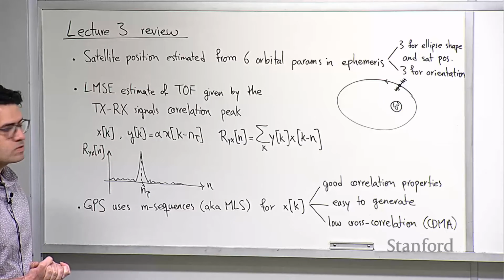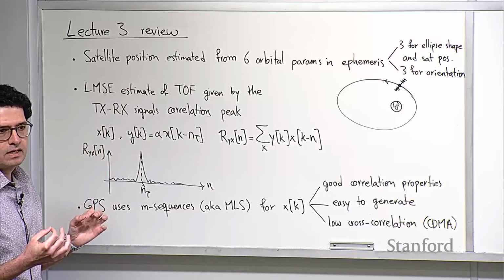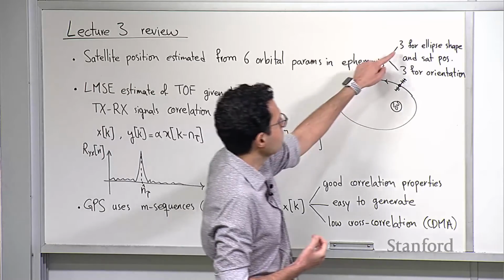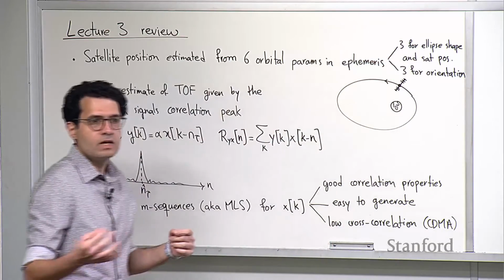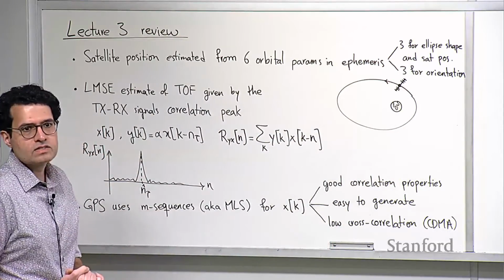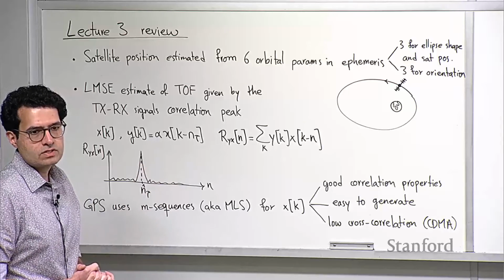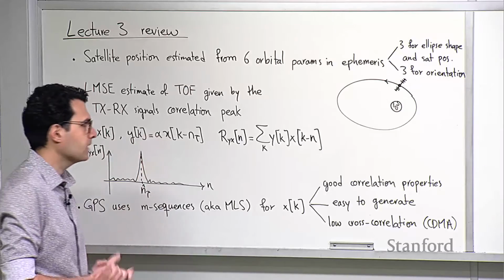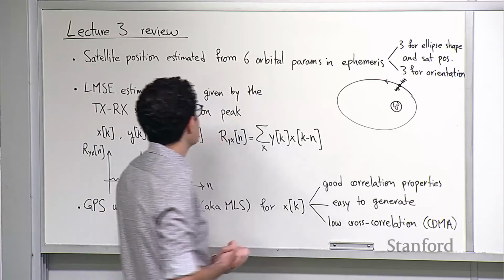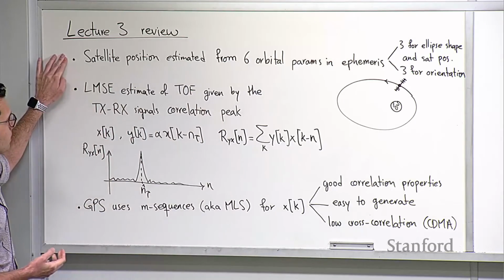point in time. There's also some correction parameters that tell the receiver how each of these 6 parameters change over time, so the receiver can extrapolate or interpolate between 2 navigation messages and continuously track the satellite's position very accurately. So that was the first thing.